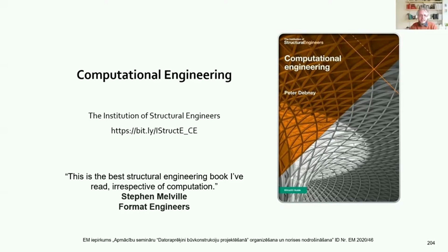Sorry, could you repeat that again, please? Could you share your experience about all-in-one finite element models for the whole building? All-in-one models. Yeah. Well, as I said earlier, if you're looking at the overall behavior of the structure, then the complete model of the structure is very efficient. If you're looking at areas of the structure, such as a connection or a floor junction, do separate models for just those areas.